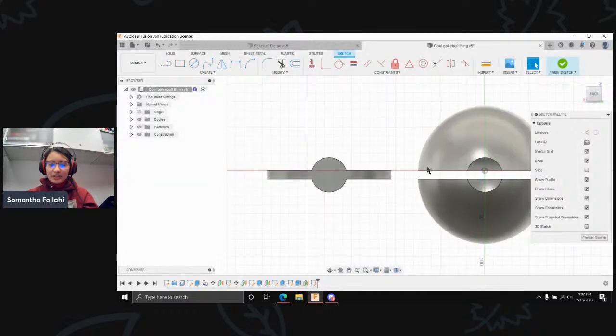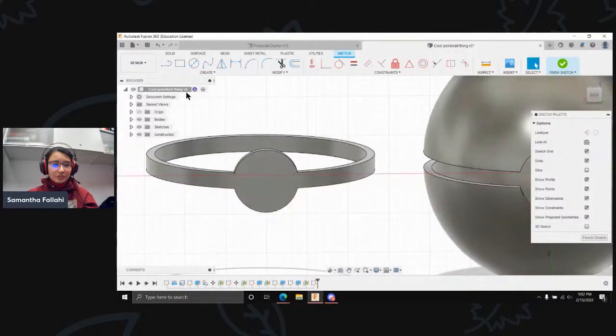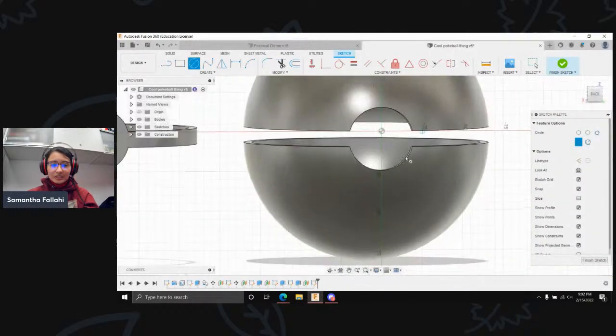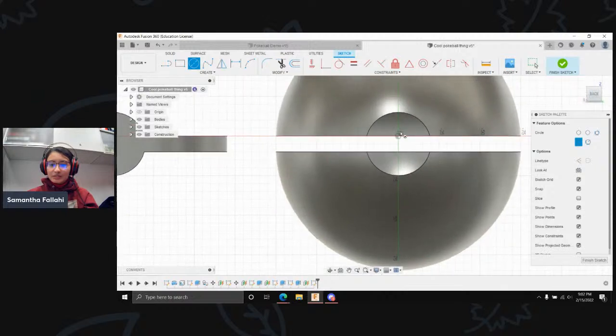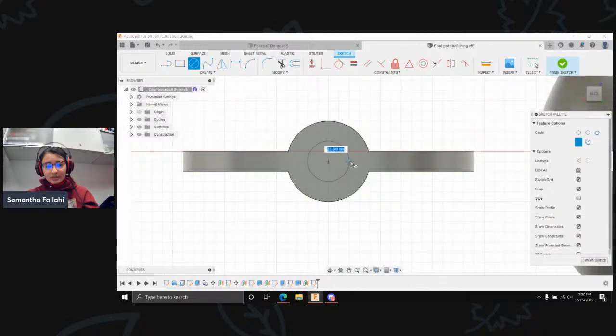You're probably wondering why I have to create a new offset plane every time. It's because Fusion really likes to just get rid of your planes after you use them. It's really, really inconvenient, but what can you do? So what we're going to do, we want to find the center of our little circle band thing. Eyeball it again. I'm going to go with 30 millimeters.